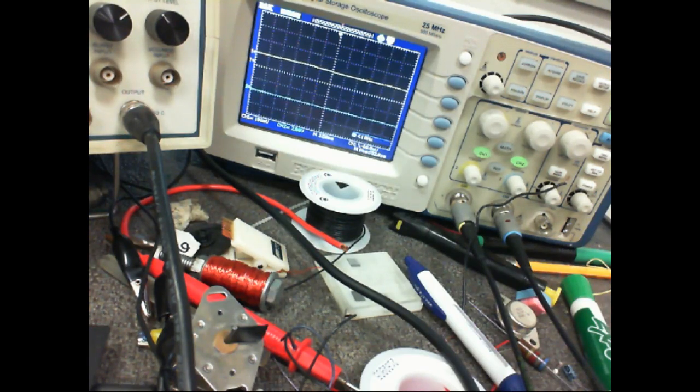But if you're running, I worked for a scale company for a while, and we had some very good conversations with people wanting to dig a ditch and run the power to the scale, and the signals, the lighting and everything in the same trough. And I said, you can't do that because your scale will be crazy. Your scale will go crazy. So in signal wires, this is where EMI gets us into trouble.